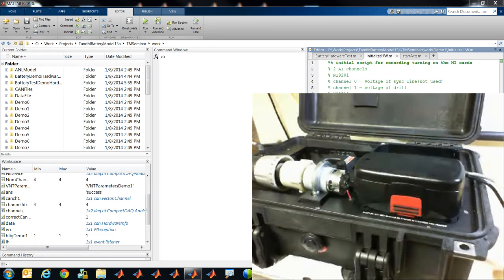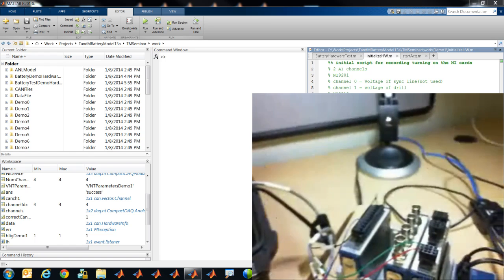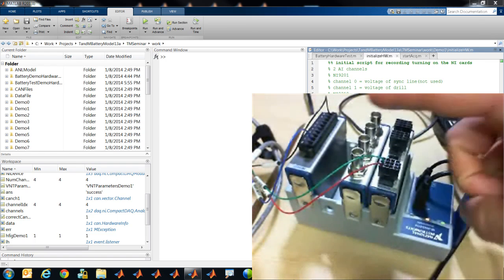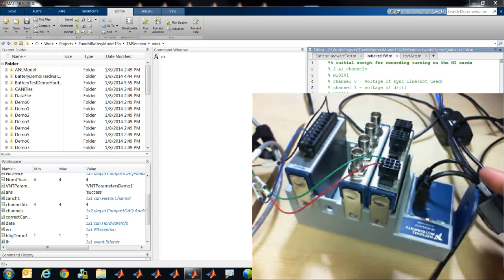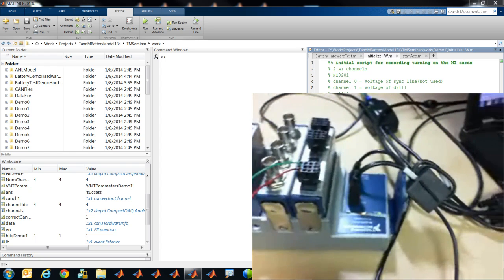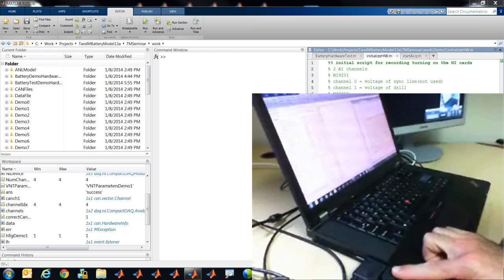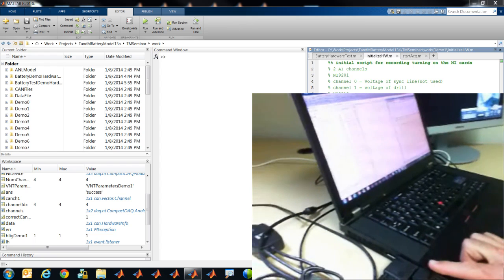We will acquire voltage and current from that battery using these data acquisition cards that are connected to the battery and via USB directly to my laptop computer. In this way, I can stream experimental data directly into MATLAB for analysis.